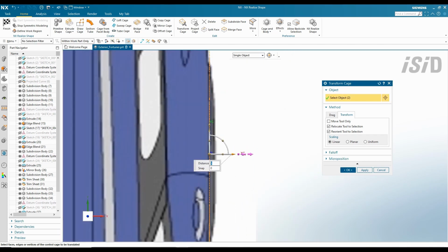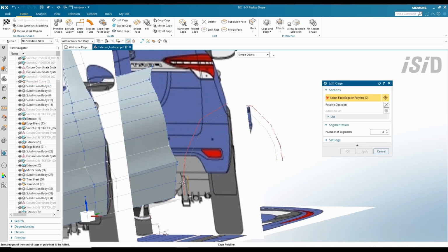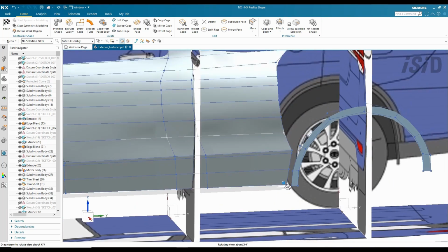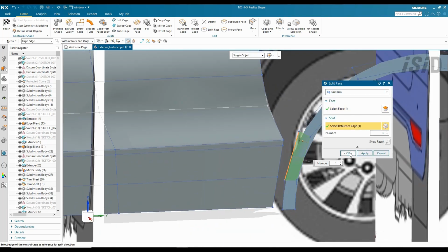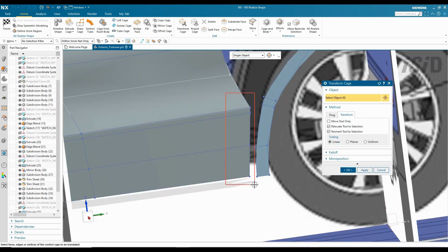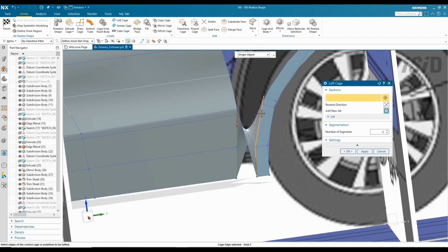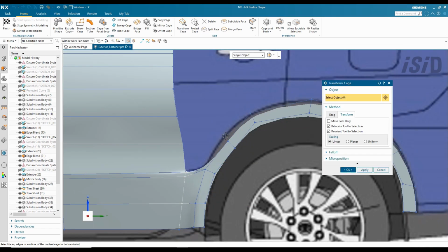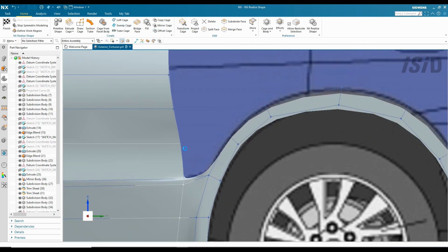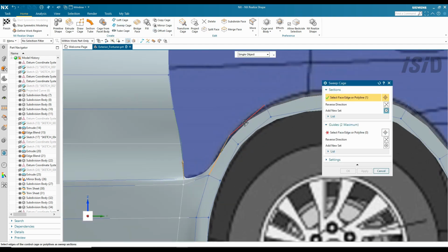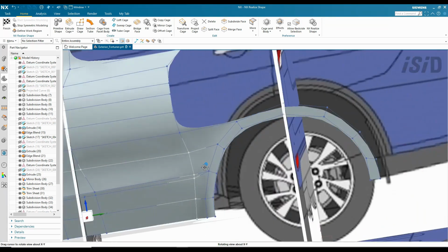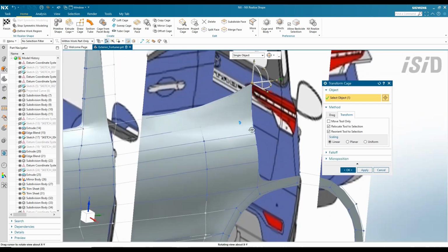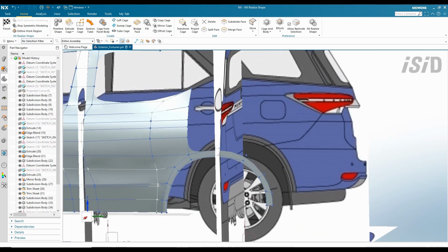And again, this example for rear fender creation using combination of cage polyline and loft cage command. And I'm going to connect this to surface using a loft cage again. And I continue to connect more surface from this area using sweep cage. And then I continue again to add more surface and more refinement using transform cage.